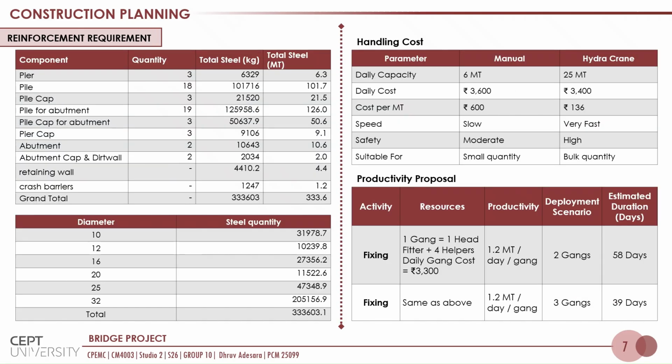As for marine and saline conditions, the reinforcement planning is vital, where for all the elements which are directly in contact with water, epoxy coated bars are used, which was the lead item for this project. For the reinforcement planning, the reinforcement is calculated based on the structural drawings, which are further distributed element wise and dia wise. From the observation, it was determined that the handling of the reinforcement was the issue.